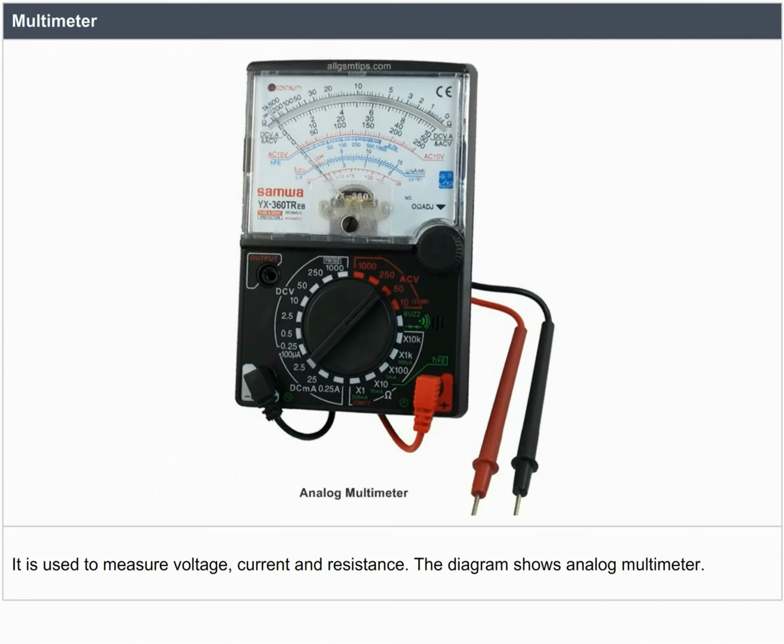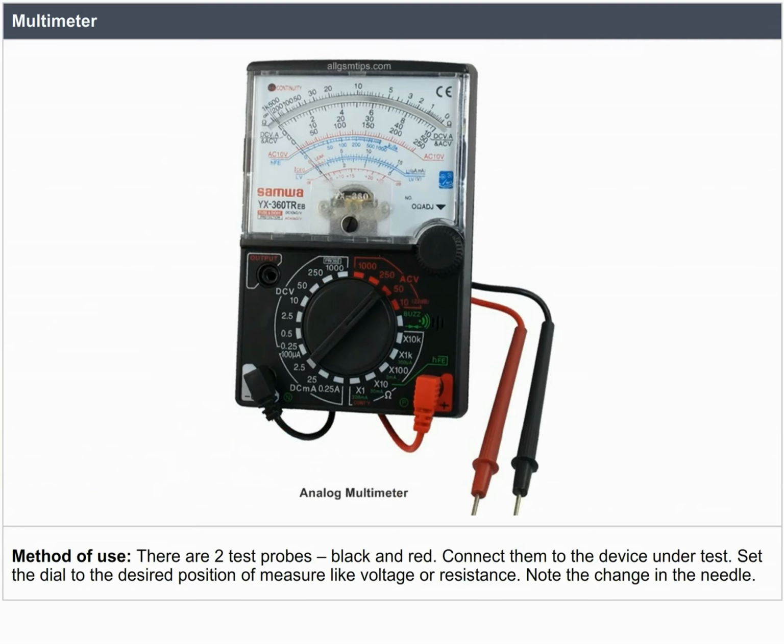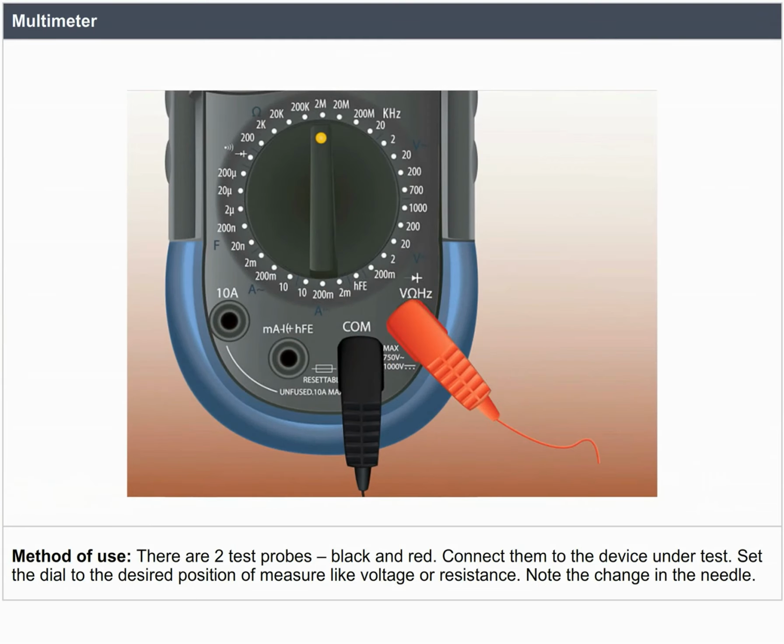Multimeter. It is used to measure voltage, current, and resistance. The diagram shows analog multimeter. Method of use. There are two test probes, black and red. Connect them to the device under test. Set the dial to the desired position of measure, like voltage or resistance. Note the change in the needle.